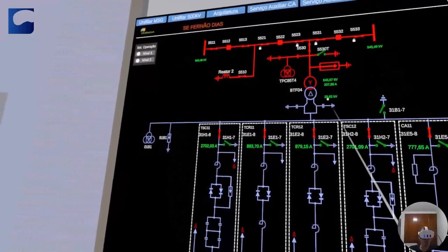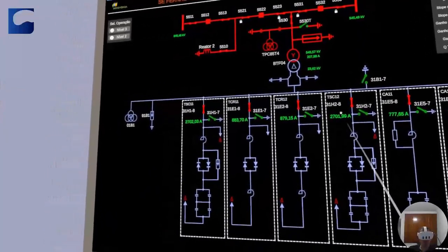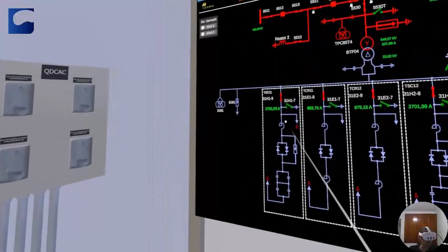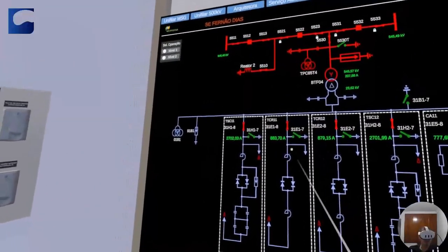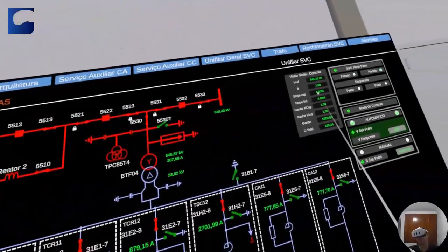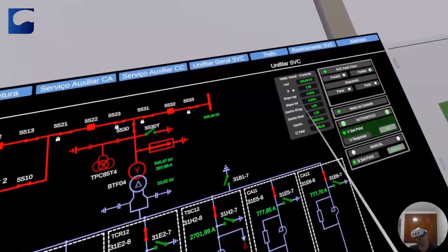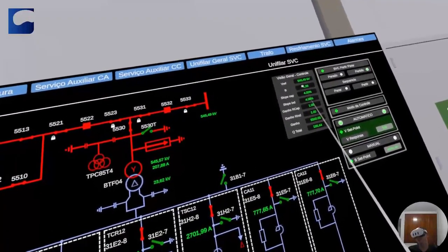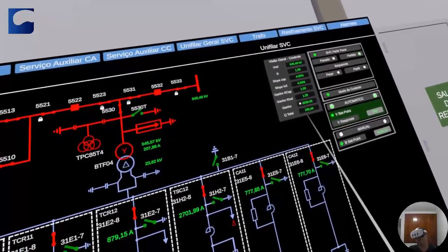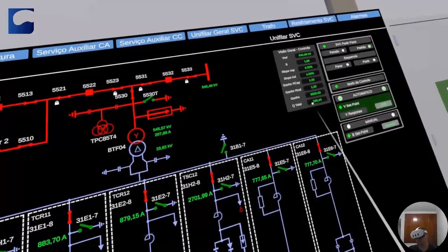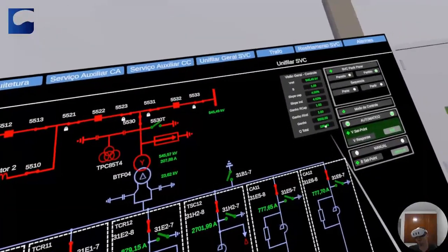It went up to 23 kilovolts here on the low side of the transformer. And look, now I have this capacitor on, and both reactors with this firing here. And here, folks, I have its B, its susceptance, at 1.98. My gain is 5,500. And here is my total Q. So if I add up my Q here, it will give this value here in MVAR.